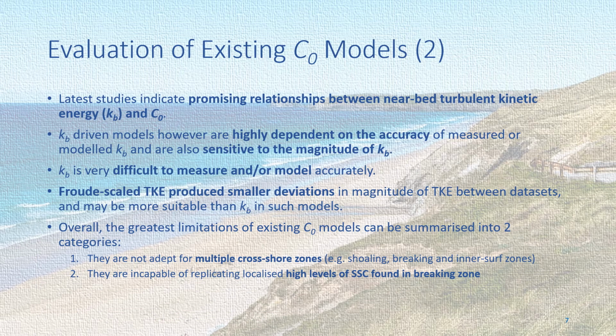Latest studies indicated promising relationships between the near-bed turbulent kinetic energy, or kb, and reference concentration c0, providing an alternative method of modeling the reference concentration. This alternative method is the direct implementation of kb values, measured or modeled. The issue with this approach, however, is that kb-driven models are highly dependent on the accuracy of measured or modeled kb and are also sensitive to the magnitude of kb.